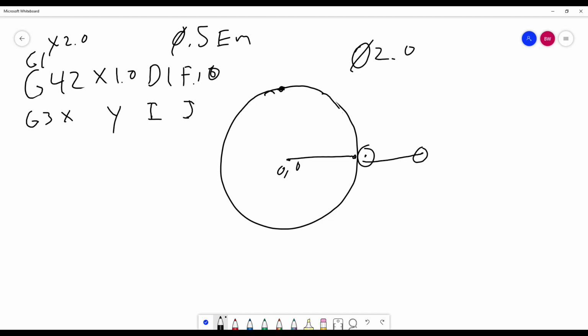So we're going to program this in quadrants. The X and Y position, where this position is right there, it's going to be X 0, Y 1.0. Comp is on. So the cutter right now is going to end up moving like right here. It has no swing data, but we want to go right here with the cutter. We need information on the I and the J. There's also an available K value. That would be for the Z if we were using it.